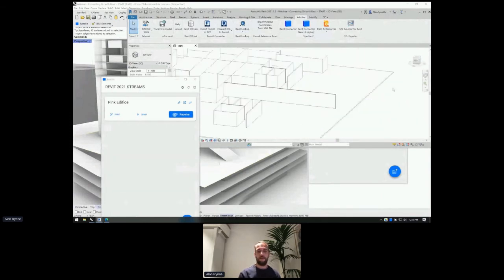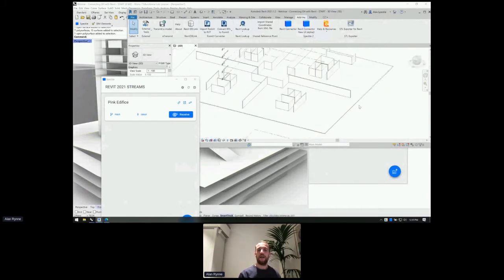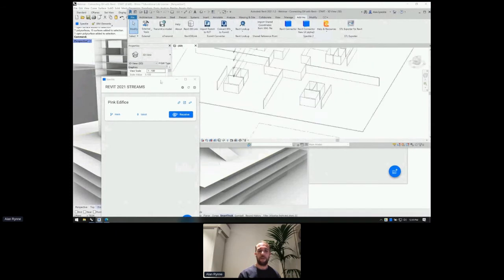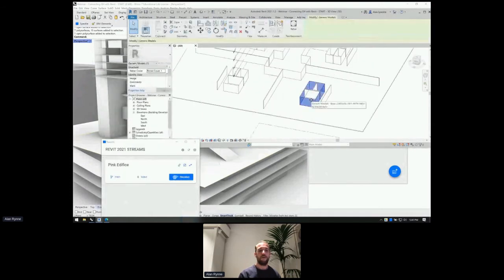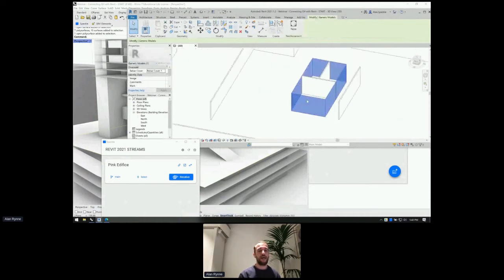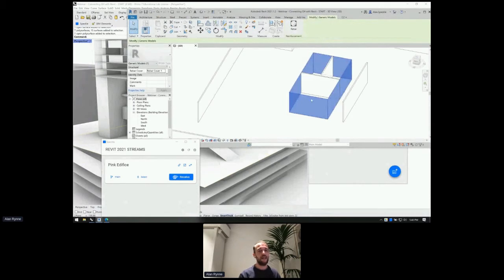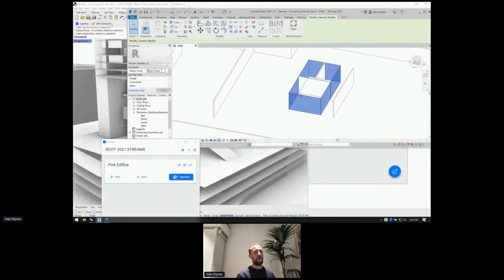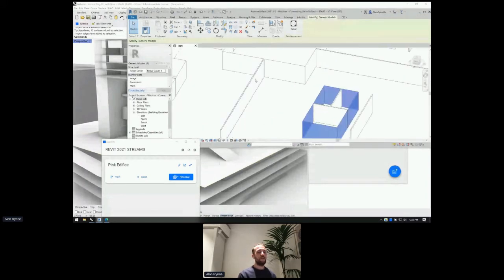In this case, all of the elements that we sent as vertical elements are now walls. But if we send something that was a polysurface, since we don't really know how to deal with the polysurface and convert it into a wall, it will become a generic element. So you can see here that there are some caveats to the whole approach.